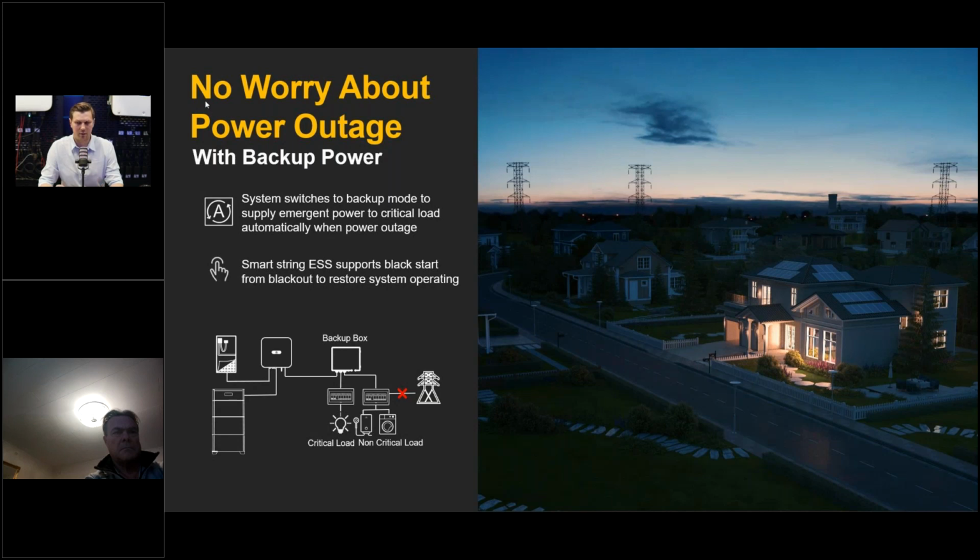At this moment, I very commonly receive the question: what will happen if we have three backup boxes and three inverters connected to independent phases? Unfortunately, it won't work as you expect, as long as you want to supply three-phase loads. If you don't have three-phase loads, it will work. If you have them, for example heat pumps, they unfortunately cannot be supplied from this backup box because we don't have the phase angle between the backup phases. This is why the system won't work properly, I mean, the loads won't work properly.